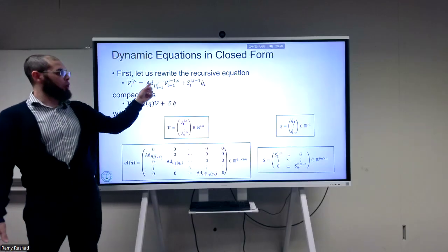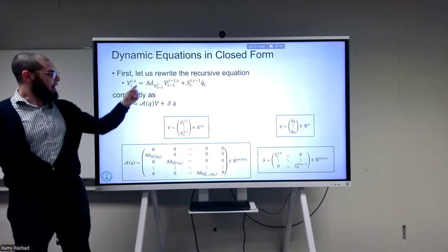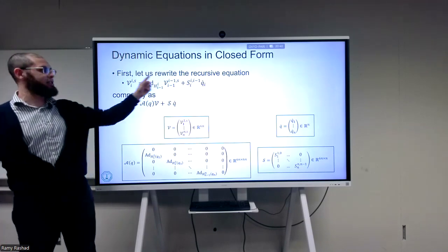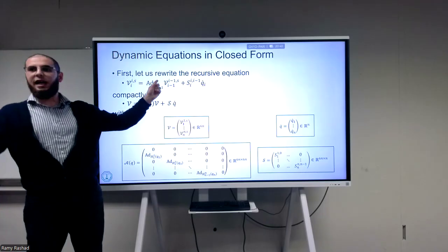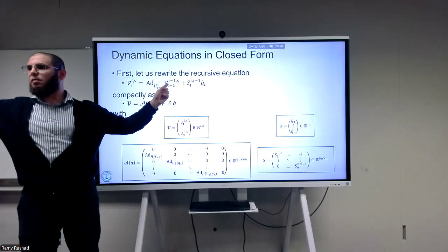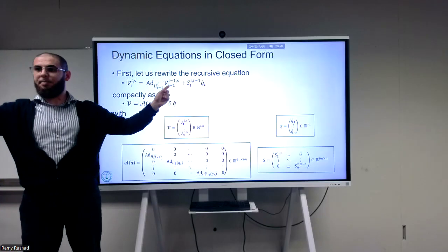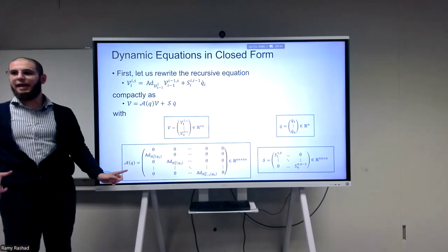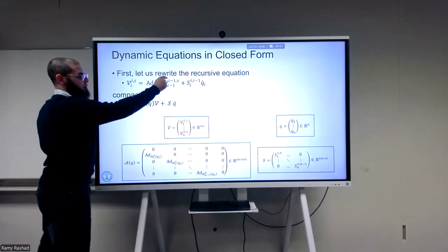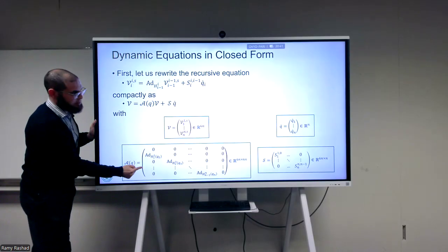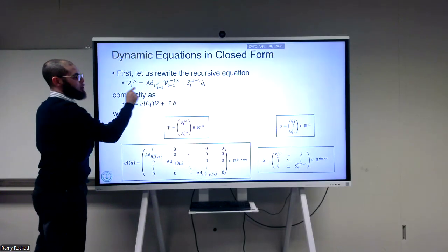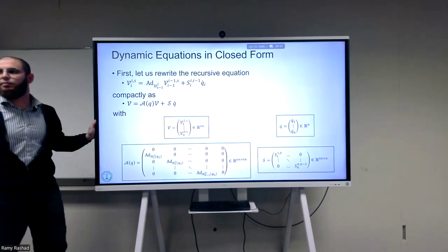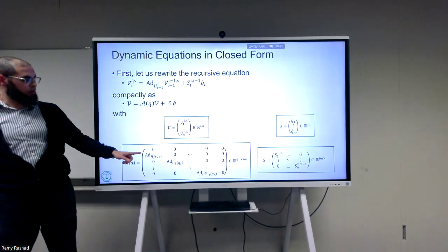And now this adjoint, you see, is multiplied by the twist. So I have here a function and a twist, but it's not the same twist. It's exactly the parent one. That's exactly what you have in this equation. I can define this A. I can combine all of this recursive part into this A matrix, such that when I stack all of these, they are given by V is equal to A of Q multiplied by V. You can test it very quickly like this.